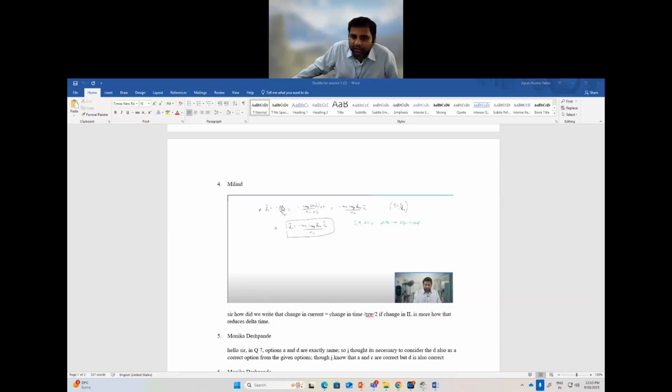For that we have the del tilde di term, and to find the duty ratio we divide it by Ts by 2, because the duty we define is the time period for which your VR voltage, the rectified voltage, is non-zero over the Ts by 2 period. That is why we take Ts by 2, and that is why we get this kind of expression.